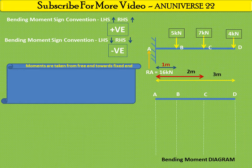We take moments from the free end and move towards the fixed end. Now the bending moment at point D. As we know, moment is the product of load into distance. When we start from D, we cover no distance, so 4 into 0 equals 0. So the bending moment at the free end is equal to 0.